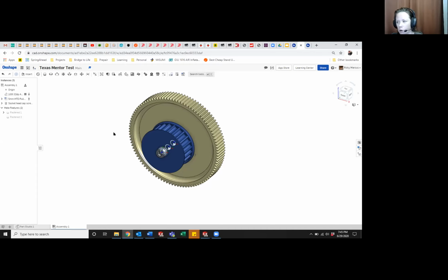I know that a lot of us don't model all the bolts in our robot, but I also know that I have personally been bit by clearance issues a number of times by not having bolt heads and nuts in place. So I thought it was kind of nice that we could force ourselves to look at that kind of detail.